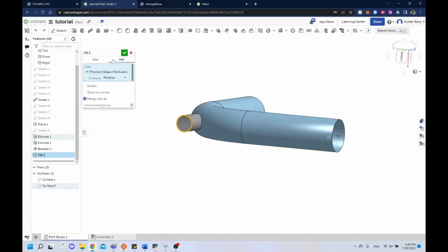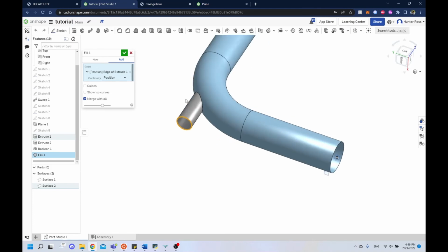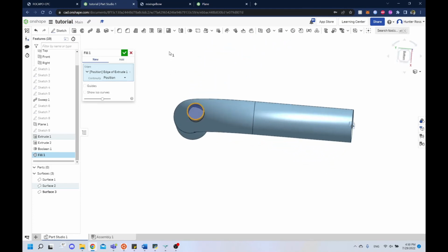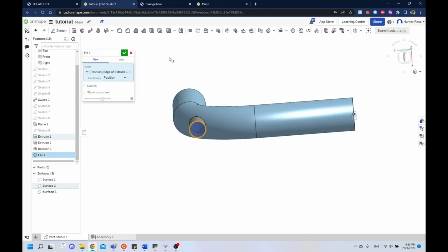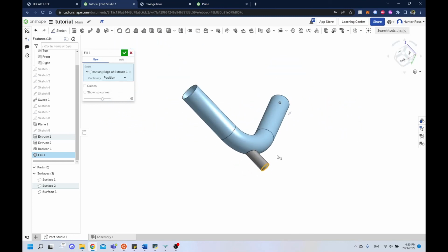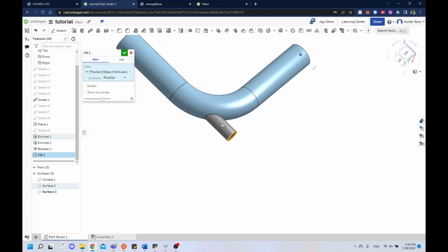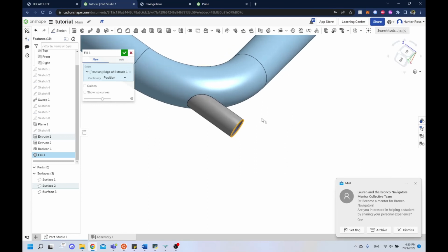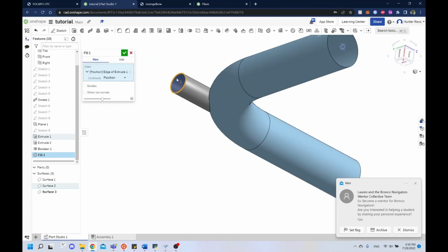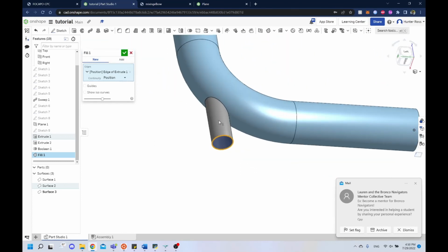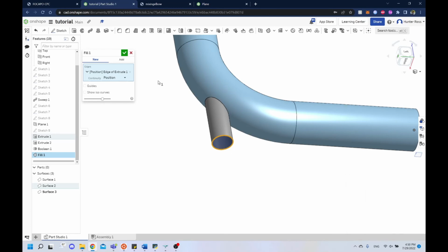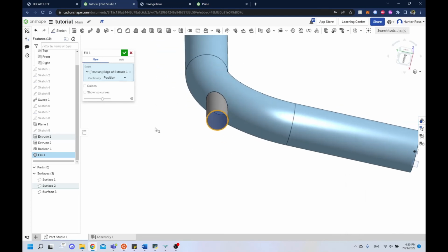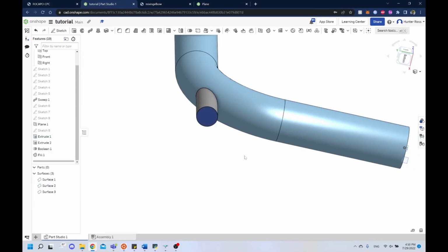Edit. I chose add, so it's saying, hey, to this surface that I selected, add a piece to that. That's actually the incorrect option here. These should be different. Because if we are simulating this in CFD, let's say that this small section of pipe is one of the inlets, then what we'd do is we'd call this face right here inlet, and this is actually where the water would be coming from. And then it would be flowing through this tube. So we want to actually make it a whole new surface, and it'll show up on this list of surfaces. So yeah, we'll call it that.